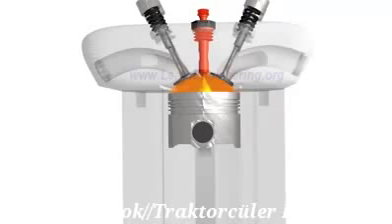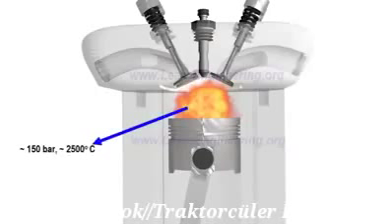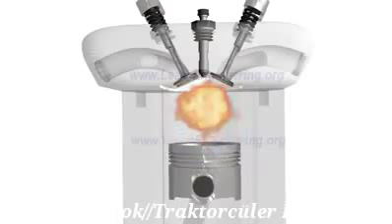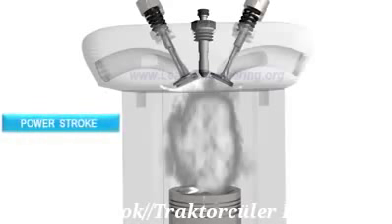The fuel gets evaporated and undergoes an uncontrolled spontaneous explosion. As a result, the pressure and temperature rise to high-level values. The high-energy fluid pushes the piston downwards. The hot air does work on the piston, and energy in the fluid is converted to the mechanical energy of the piston. This is the only stroke where the piston absorbs power from the fluid.